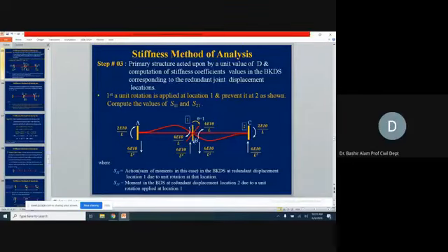But now you keep in mind how this rotation is provided. First, at this fixed support, we release the moment. How we release it, we make it a hinge support, and at the hinge support we provide theta equal to 1. That hinge is not shown here, but with this red line the rotation is shown, that this support is rotated to this location. And as a result, this is now the distorted shape of the structure.